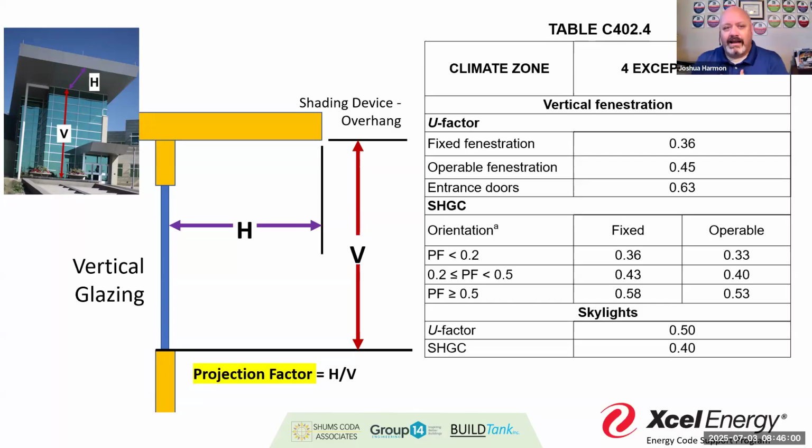So as a plans examiner, I'm just making sure it meets the minimum requirements. But as an inspector, I'm making sure that it's in the right spots. And one of the things when we start talking about mechanical heating and cooling load calculations, and we'll talk about that, I think in a couple weeks we'll get to mechanical, is that I'm actually verifying that the mechanical load matches my insulation values.